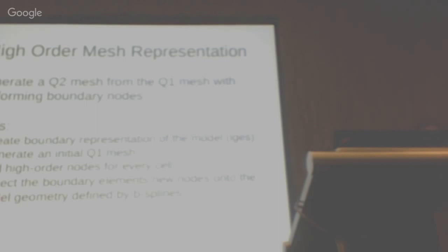You have plenty of options, but one that would work generally for different kinds of geometries was not directly available. So we chose to read the definition of a CAD geometry based on an IGES file. By reading the data in the CAD file, we reconstruct the geometry with either a B-spline or a NURBS surface, and with that in memory, we can correlate with the middle node of the face, then we project it. So besides the edges that lie on the boundary of the domain, you also add the middle node at each edge of the cells throughout your whole domain.